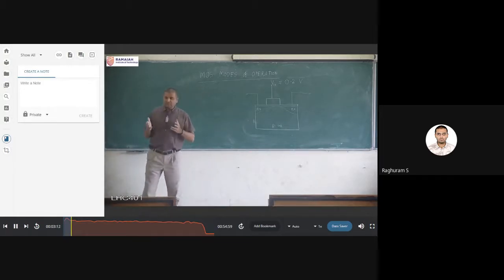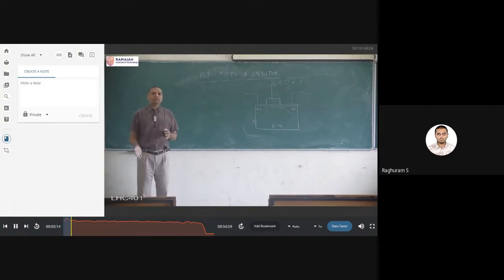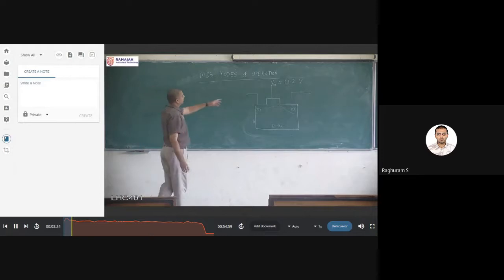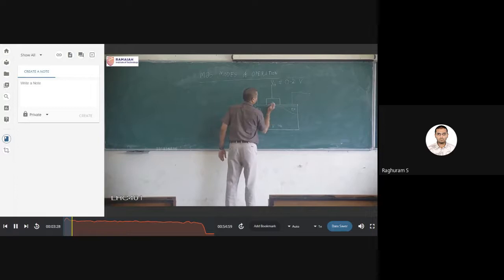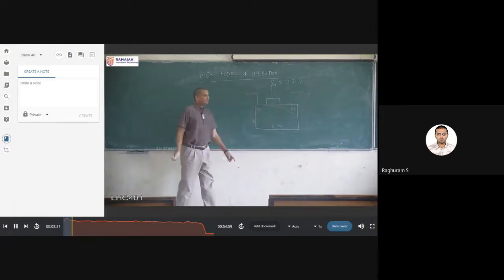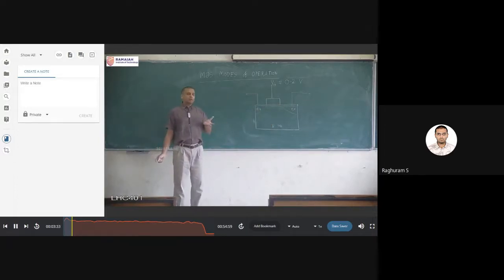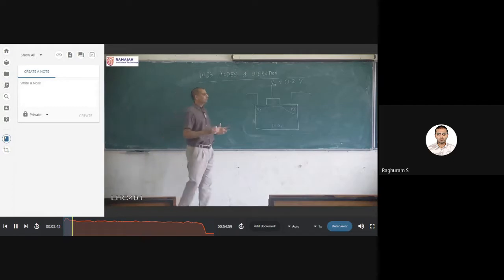Whenever my transistor goes from conducting to non-conducting, the channel region is the one that is going to determine that condition. So we will look at the channel region again. Now I am applying a small positive voltage. What will happen in the channel region? First, the holes. There were a lot of holes through the substrate, and in the channel region also holes were there. But now because of the positive voltage, the holes will get pushed away. There will be very few holes in the channel region.